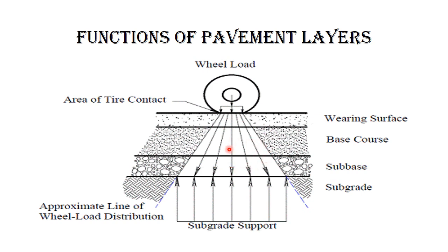Above that there is a base course. The main function of the base course is to support the surface course. The granular base course is considered the most important component of the flexible pavement, which sustains the wheel load stress and disperses it through a larger area on the GSB layer. A good base course enhances the load carrying capacity of the flexible pavement structure. Good quality coarse aggregates are generally used in the granular base course of flexible pavement.